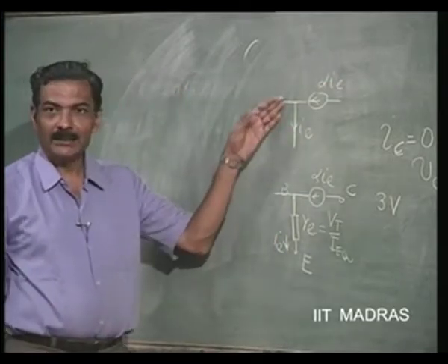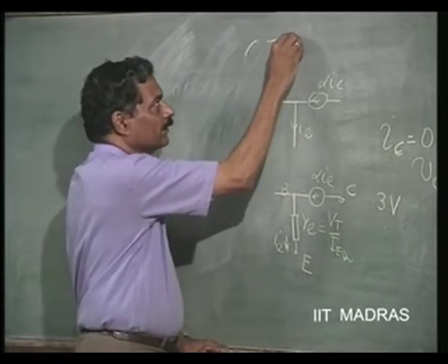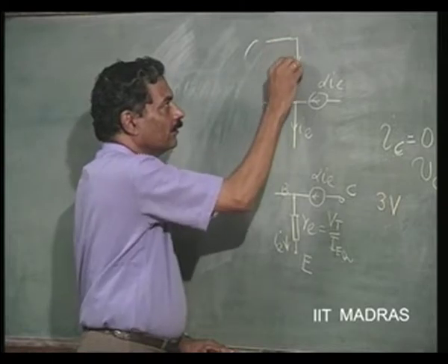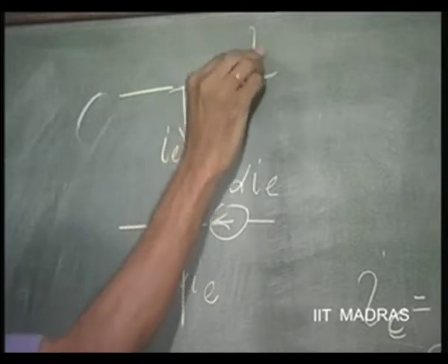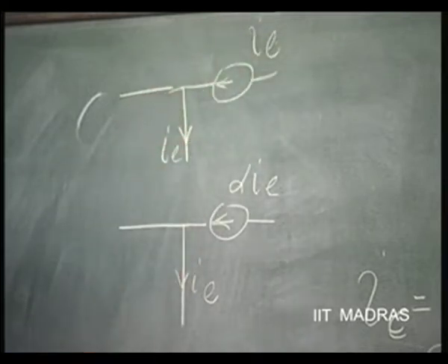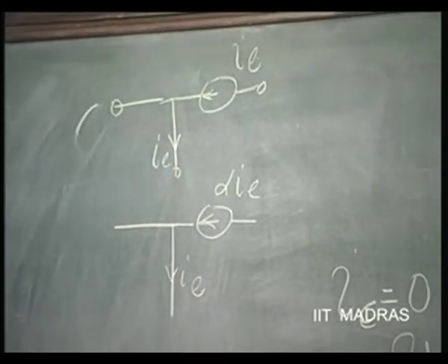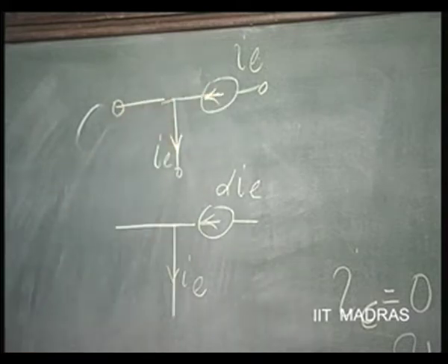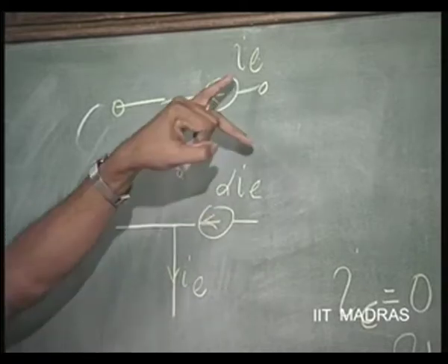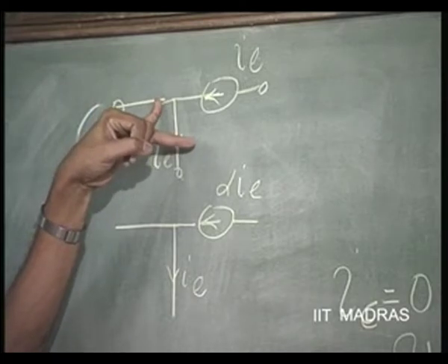This is simpler than this, right, and further we just said this is IE, this is IE, alpha equal to 1, the ideal transistor equivalent circuit. And you see here, if you represent this by an equivalent circuit like this, IE is the current source current here. That means the current in this is always 0.